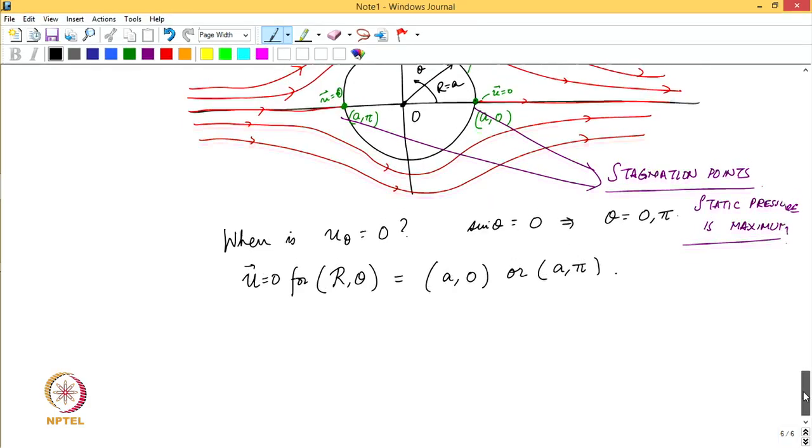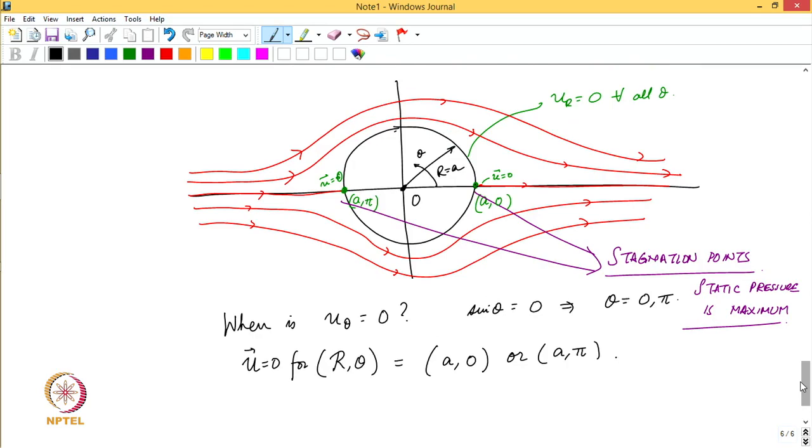As we are dealing with irrotational flows, there is no shear force on any solid object. So, there would only be form drag, and we will derive what the solution would be using the same complex potential method. I hope that this part is clear, and we will take it further in the next lecture.